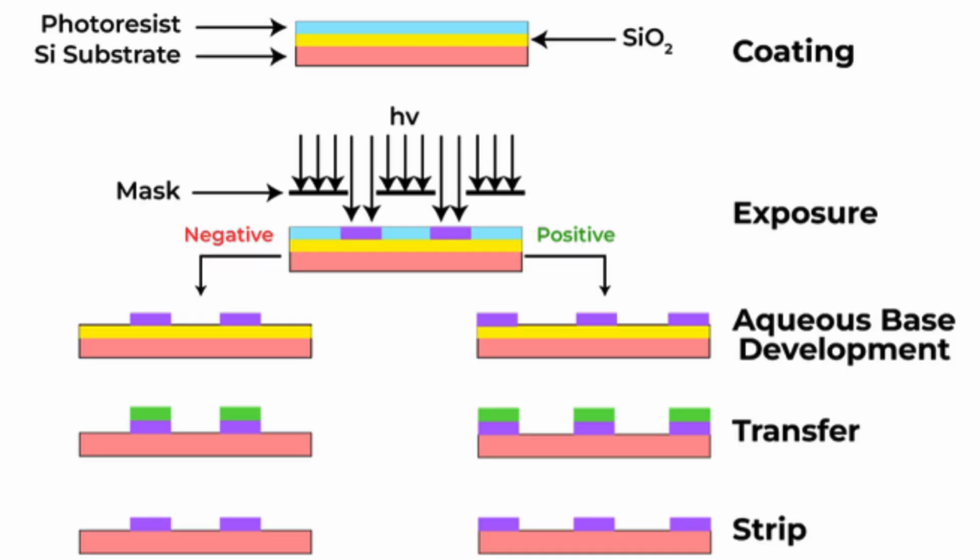The design is transferred to the wafer via photolithography, printing with light. A light-sensitive chemical, photoresist, is applied via film coating. UV light is shined through a mask, the circuit's blueprint, selectively changing the chemical structure of the photoresist. Then the developer washes the exposed areas, giving a template for the next step, which is called etching.